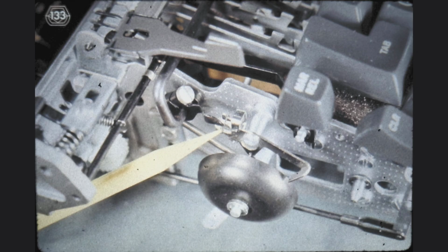All of this must be accomplished with the motion obtained from the first step of the line lock bracket, which is transmitted to the bell ringer bail. Be sure that the bail lever is also properly restored above the indicated spring when the bell ringer bail is allowed to return to rest, and finally, that the bail has enough end play to operate freely. Take the time to check all of this now.